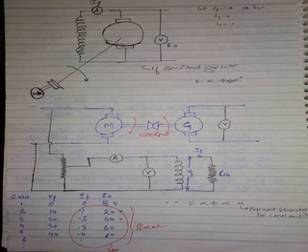After that it becomes saturated. Means even though the current increases in the field winding, flux won't increase, then voltage won't increase. So now if you plot a graph between different values of IF, different values of E0, you have to record, for each voltage current value, what is E0, keeping speed constant. Take some 10 or 12 readings, sufficient readings.